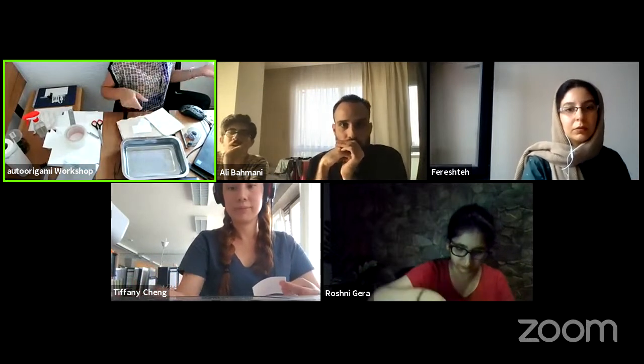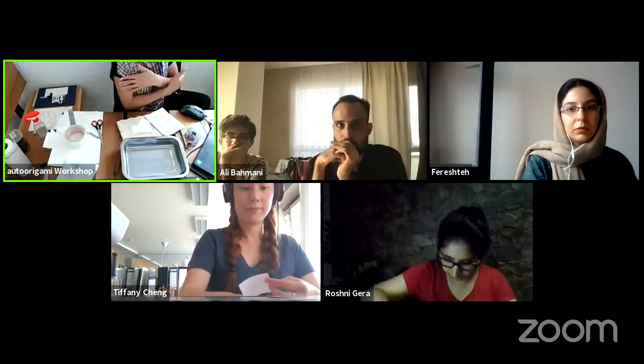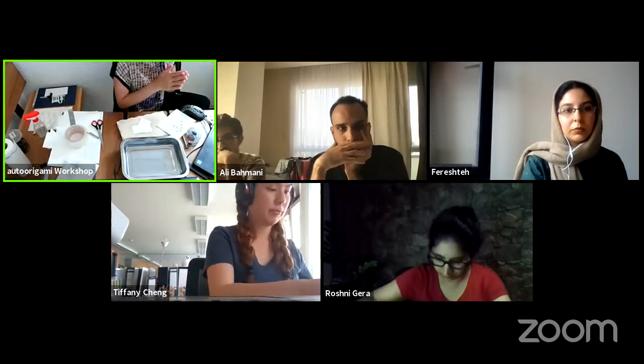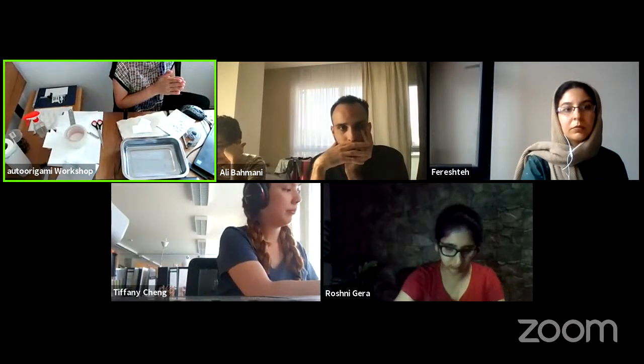So let's think of the application when we want to put it on body or on facade. We want to decide if we want things to be open when they're wet, or if we want them to be open when they are dry. And based on that, we decide. We do the same thing. We put the wood in high moisture for a long time, and then laminate it, make the bilayer.